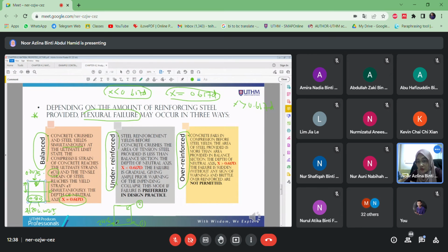The same load is applied, still 100 kilonewtons, the same load applied here, about 100 kilonewtons. So you can think logically. Once you apply the same load but with a different arrangement, or once you slightly reduce the diameter or size of the reinforcement, the steel here will reach its limitation first, reach its yield strength, and after that is followed by the concrete here.